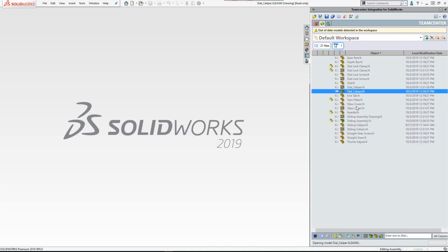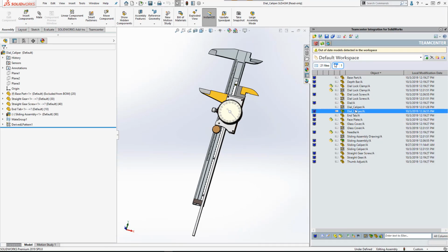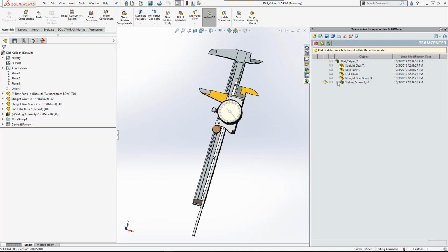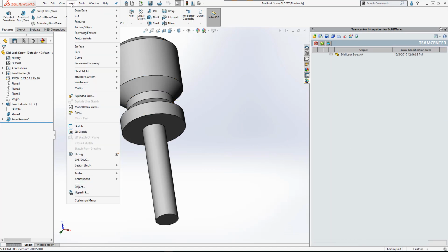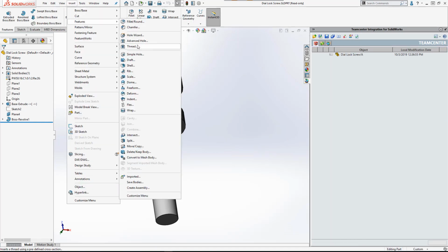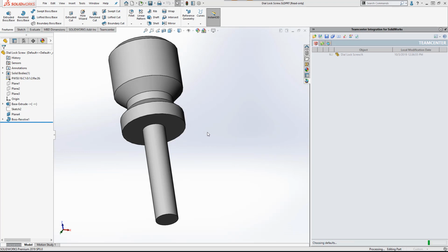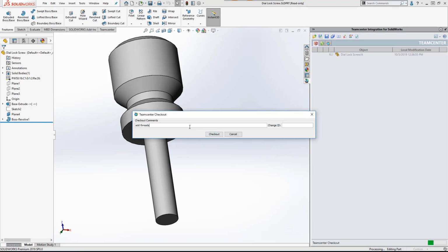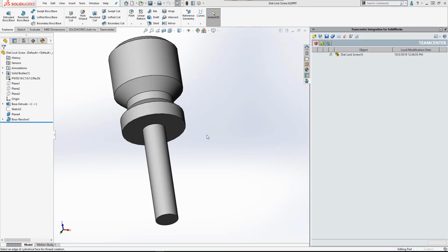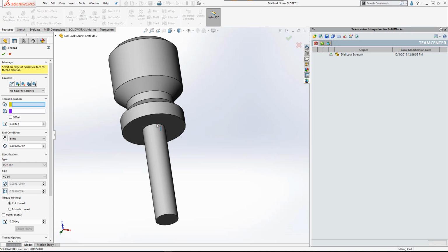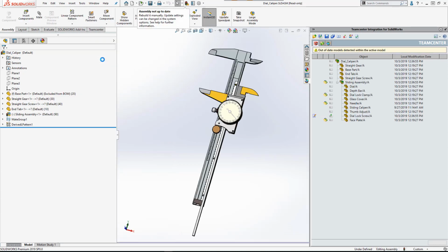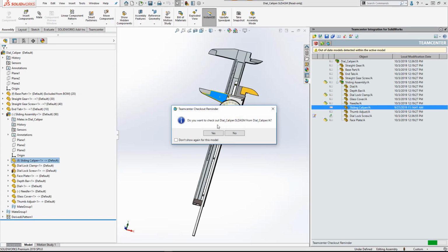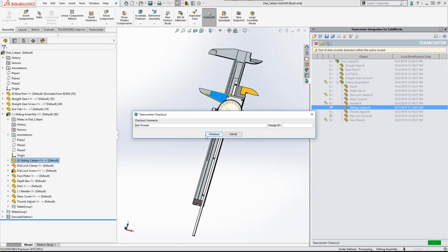When a part or assembly is modified in SolidWorks, and then saved to Teamcenter, any associated drawings should be updated and saved as well. The integration now automates this task by detecting cached drawings related to modified 3D models that are being saved to Teamcenter. Please note that modification is the trigger. There is no reason to update and save related drawings unless their 3D models have changed. If the drawing itself is changed, independent of its model, then it should be explicitly saved on its own.